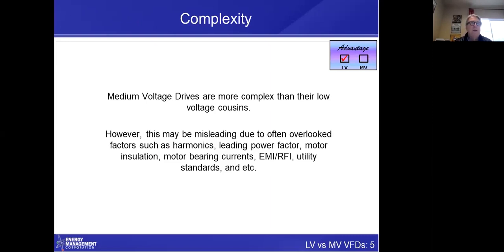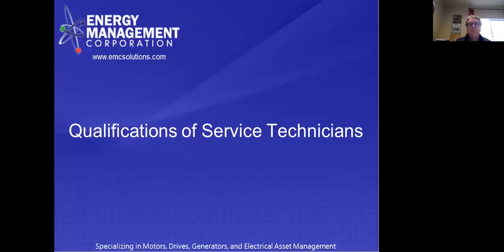However, this may be misleading because there are other factors when you use low voltage drives that don't necessarily apply to medium voltage drives, such as harmonics, leading power factor, motor insulation, motor bearing currents, and so on and so forth, which we will get into in this presentation.